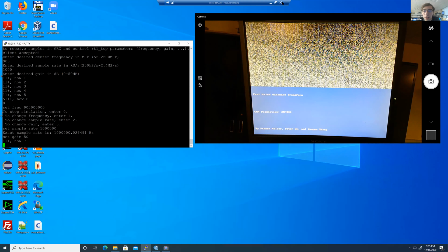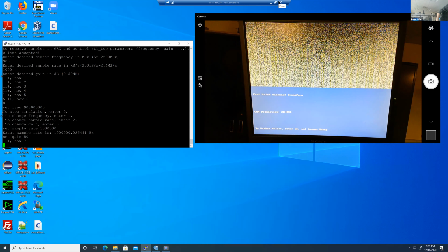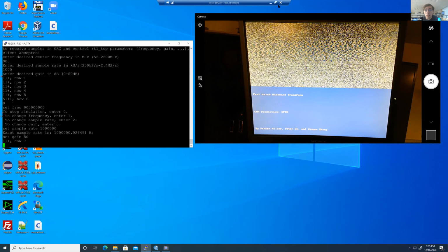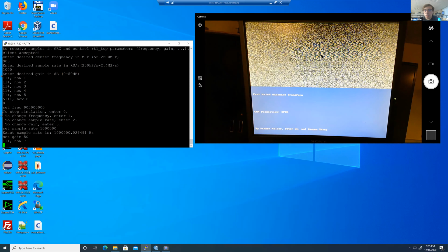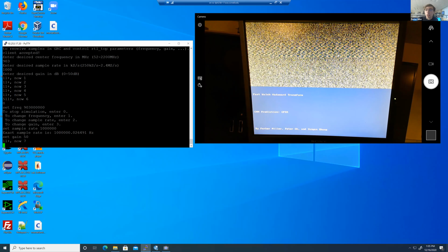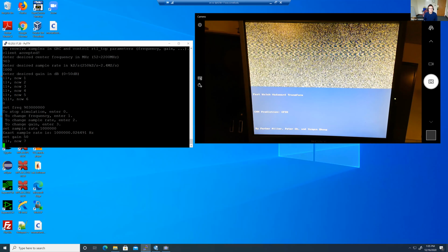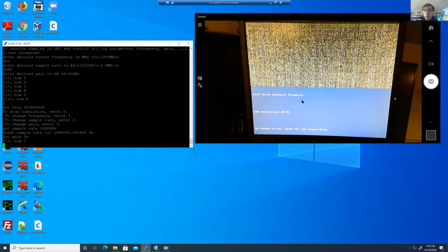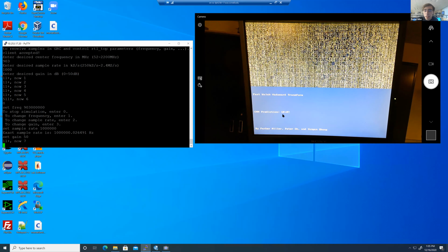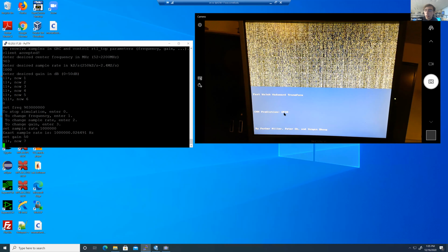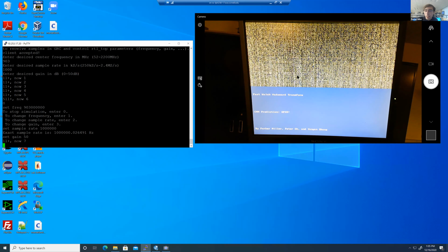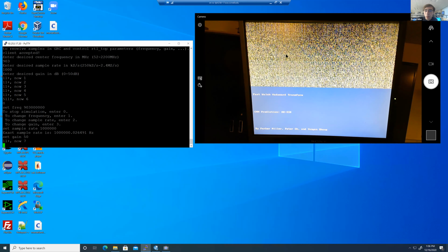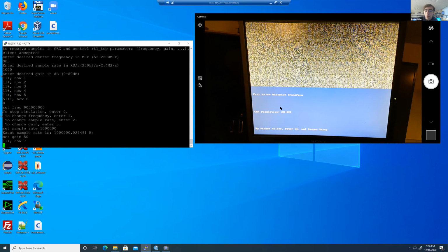Okay, so we have all the pieces in place, but that is actually GFSK based on the spectrum we're getting in the imagery. You can see the lines there. And then it's actually, I think, going to FM right now. So you can see it trying to guess, and it's not sure whether it's GFSK or FM, which is a side effect of just a relatively small neural net. And then it's going to go back to AM, which it predicts pretty well.